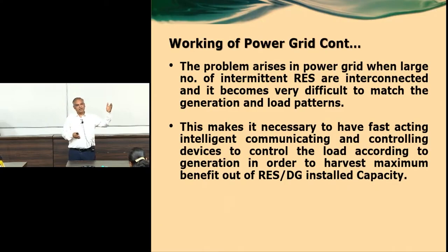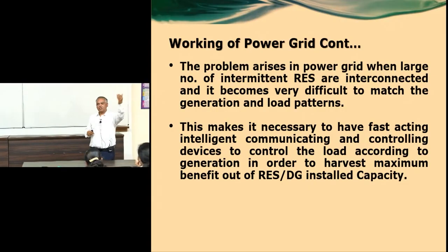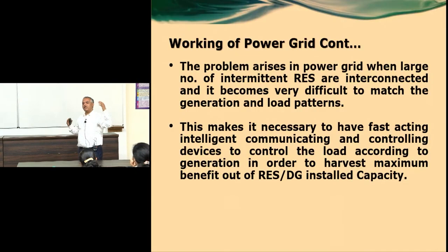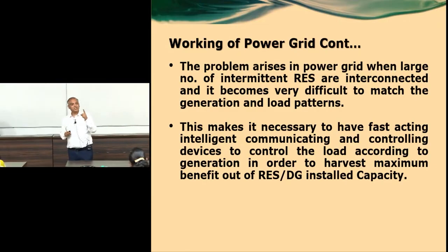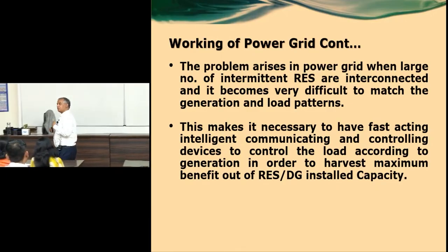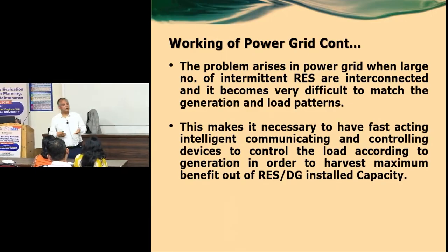Because in North America, including Canada, I say North America, US and Canada, the centers are spread out and there is no population, nothing is there. More and more first generation wind turbines, self-excited induction generators, were installed over there, and they were consuming a lot of reactive power in comparison to whatever active power they were supplying. So they were having more of a lossy impact on the system rather than producing some fruitful active power.